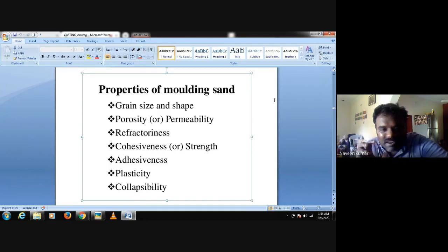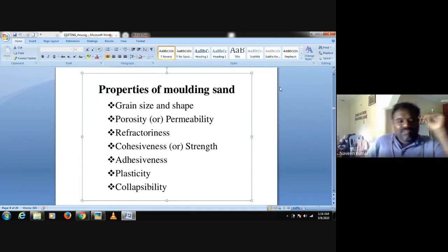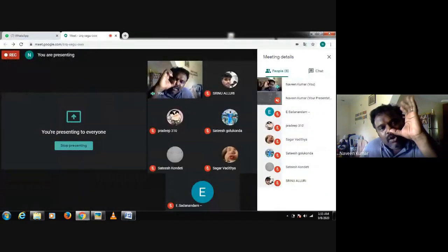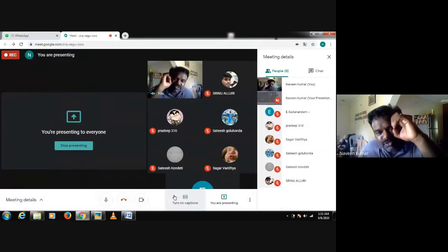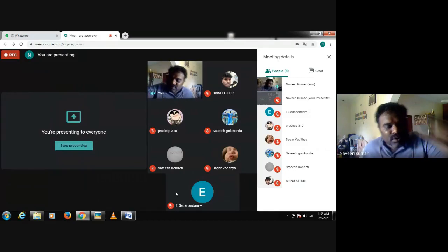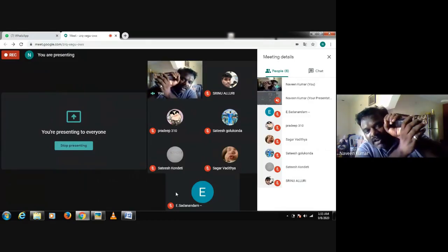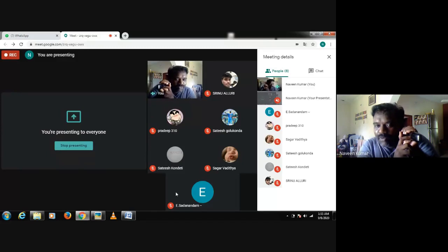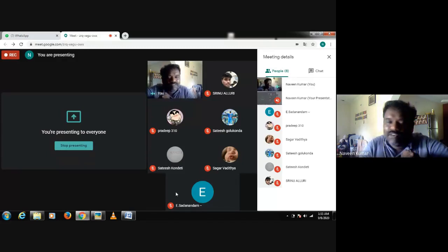compressive forces. Whenever cores are used and allowed for solidification, we know that molten material contracts on solidification. On contraction, the molten material produces compressive forces, correct or not? And these compressive forces are exerted on the core. So the core should be able to reduce its volume by itself under the compressive forces generated due to contraction of the molten material during solidification.